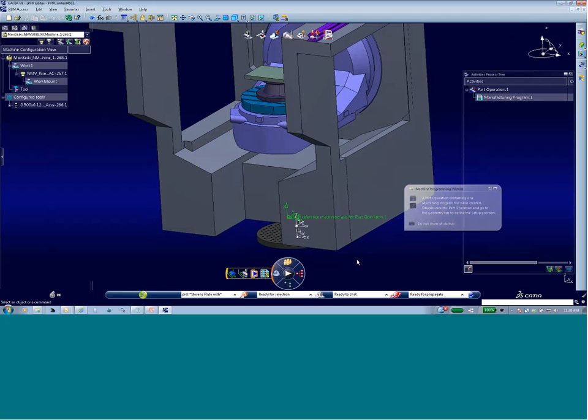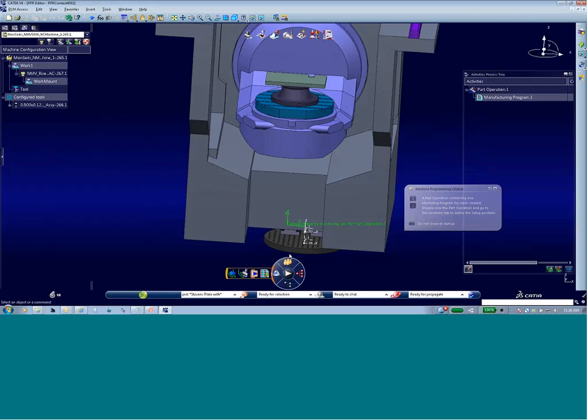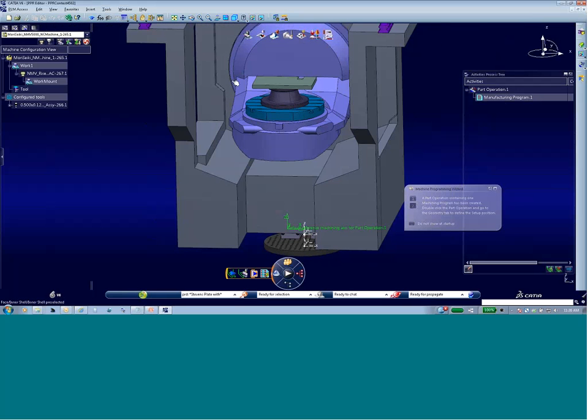The machining cell can also have accessories for that machine defined. In this case, when I stored the machine last time, I had a machine accessory, which is a riser mounted to the table. So instead of my Stevens plate with the V blocks, I had a riser for a different setup.